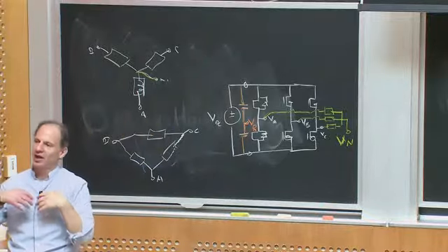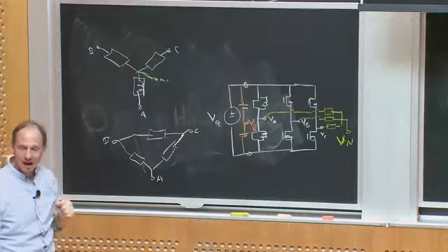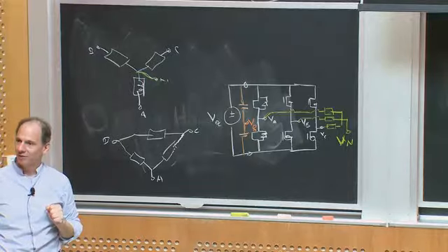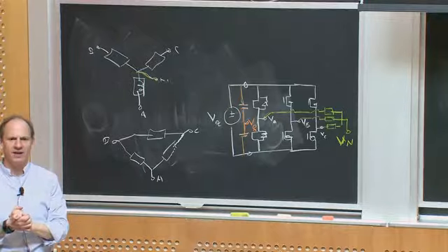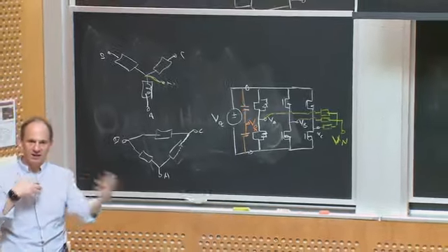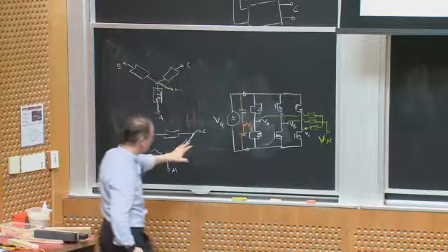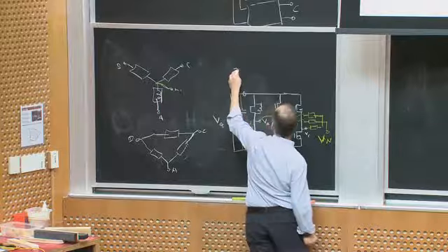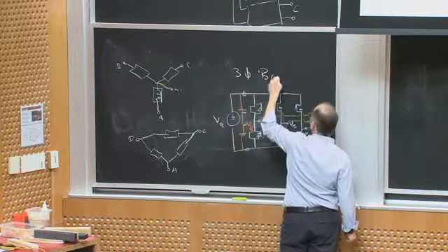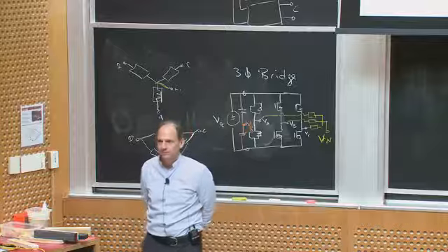So in very specialized high speed machines, for example, you might go for the top solution of independent phase drive if you're allowed. But the vast majority of 3-phase inverters or 3-phase DC to AC converters, where power could flow either direction, where you have active control, is with this 3-phase bridge structure. Any questions about that so far?